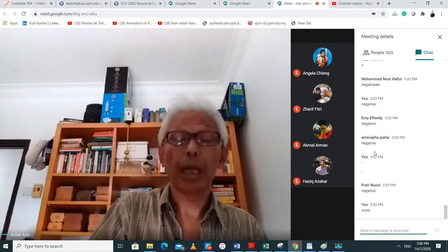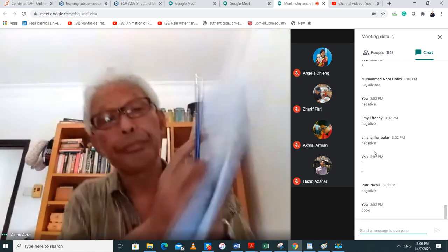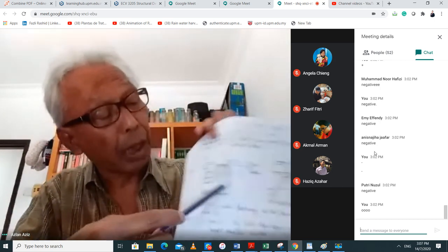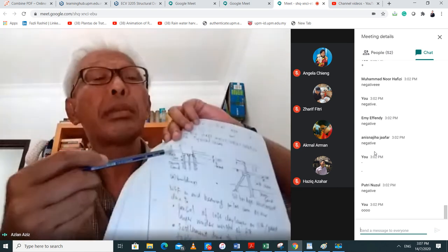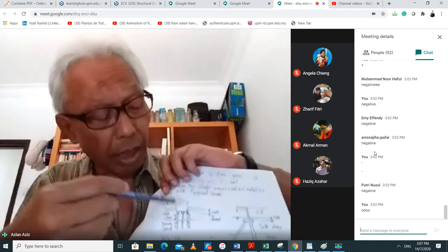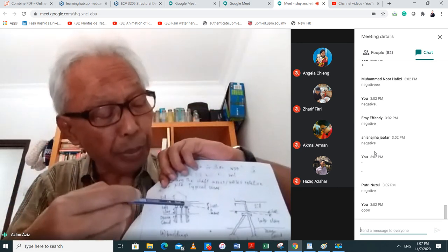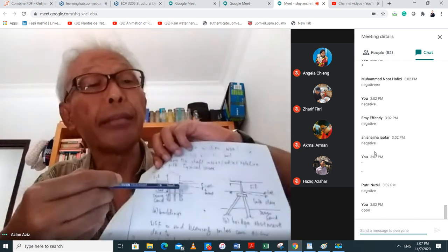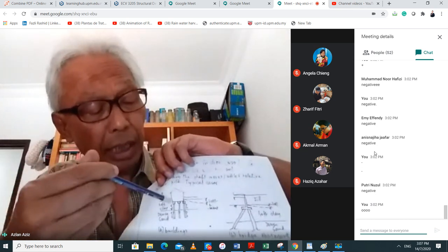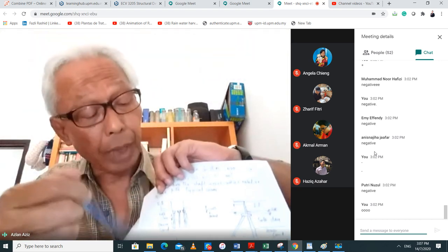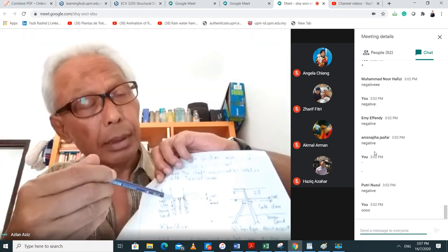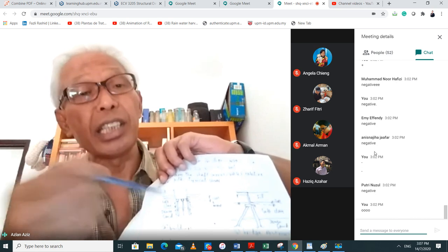So the NSF, negative skin friction, reduces the supporting capacity and increases the axial load in the shaft. Okay, you see this picture here? If this is, say, some clay that doesn't experience this fill settlement, in other words, you don't get the shaft friction in the negative direction.